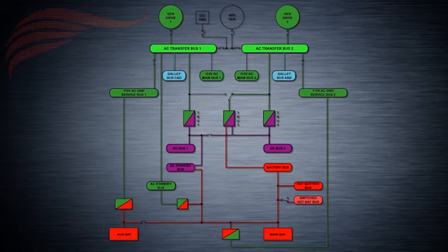AC transfer bus 1 subdivides into the following buses: AC main bus 1, AC ground service bus 1, galley bus C and D, and AC standby bus. The AC transfer bus 1 also supplies electrical energy to the DC bus 1 through a component known as a transformer rectifier. We'll discuss AC to DC energy transformation and DC buses later in this lesson.